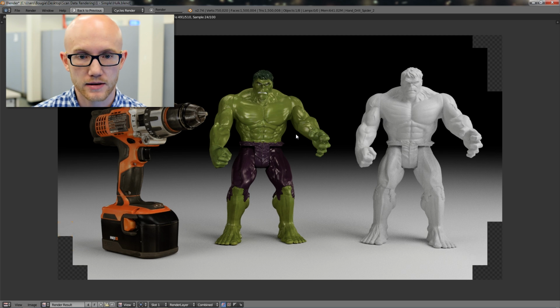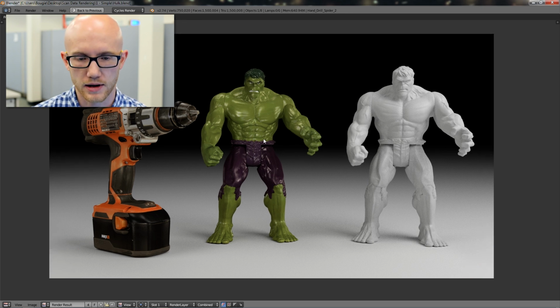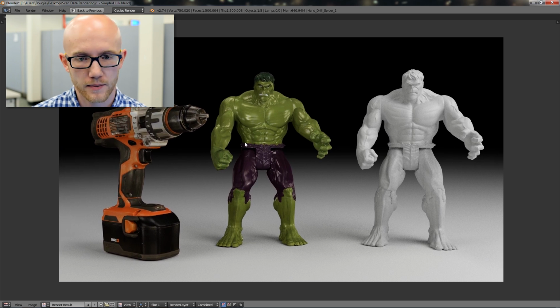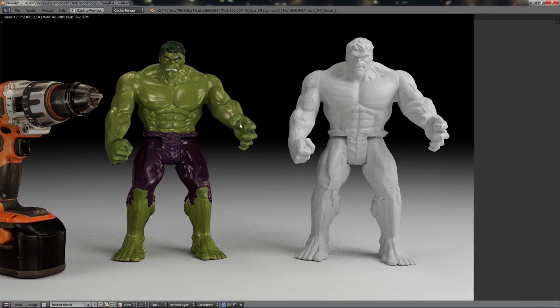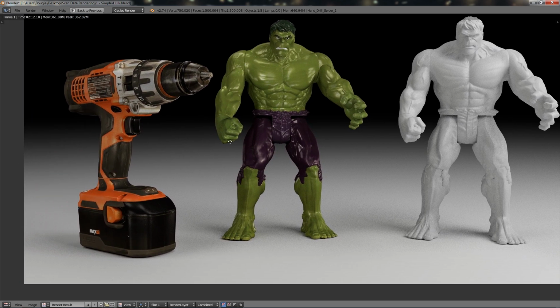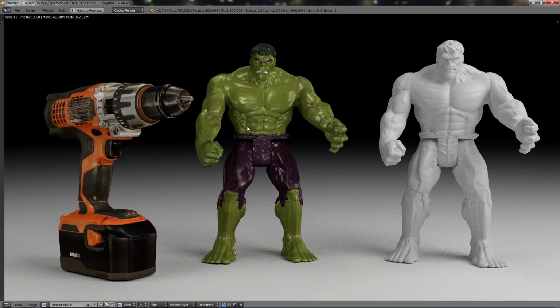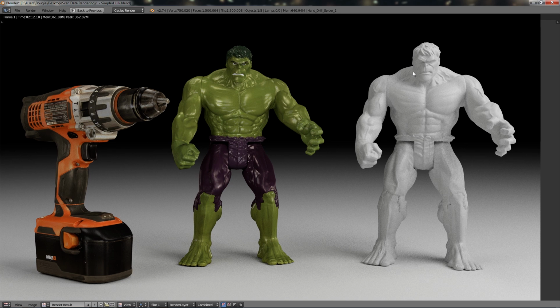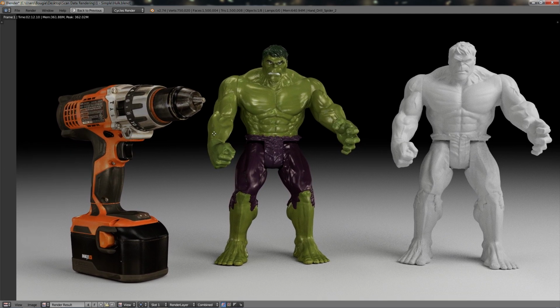Okay, we are just about done here. And that is complete. Again, when I'm in this render viewing window, I can press 1 on my number pad to zoom in and go to 100% view. I did this at 1920 by 1080, so that's why it doesn't zoom in as much. This is 100% here. You can see it looks pretty good, but I've got some grain here. That's because I only did this at 100 samples. To get rid of that grain, you just increase your samples.